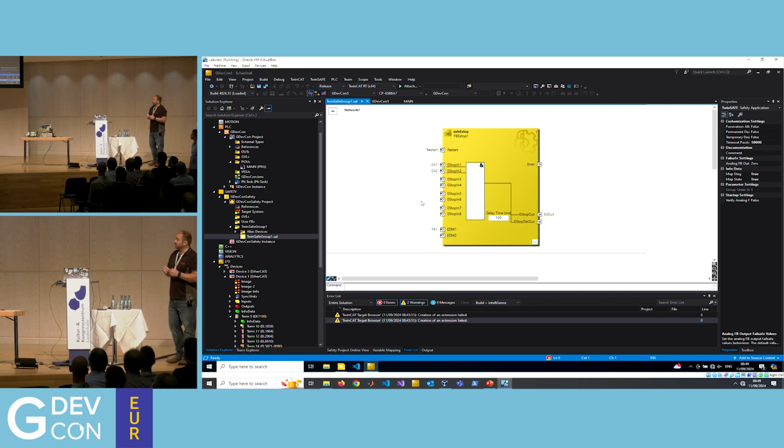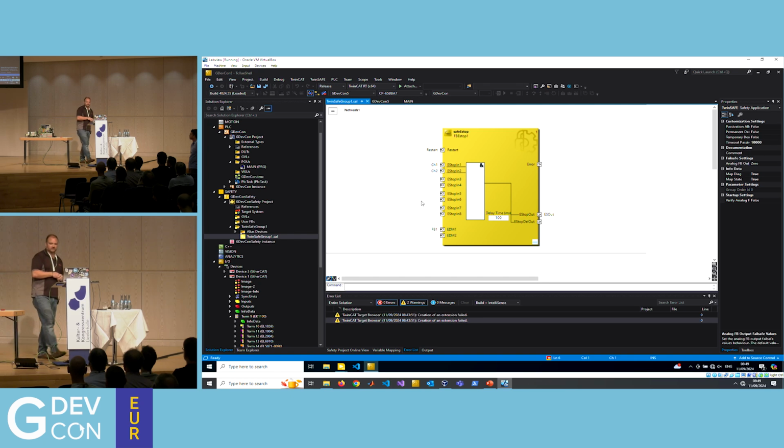So it's been quite useful in automation because it's moved us away from having a cabinet that's just safety and running a lot of wiring back to that cabinet, to pushing islands of I/O like these two here, with safety terminals integrated much closer to the machine where the actual contacts, relays, whatever they need to be near, are.